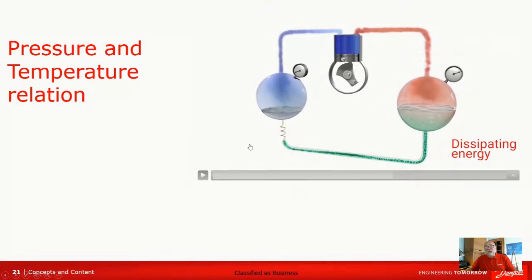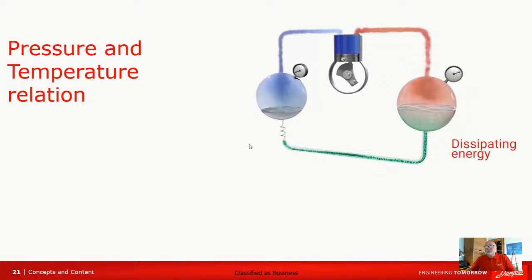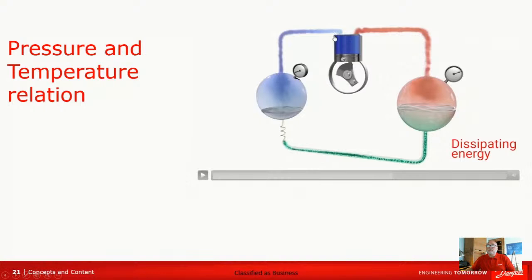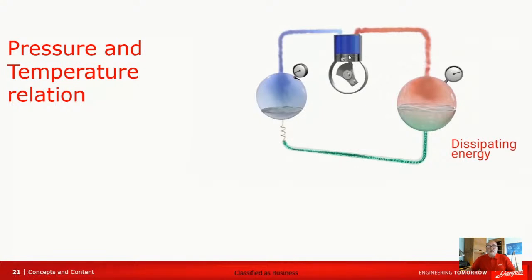So in principle, on a reciprocating compressor, if it turns one way or the other, that doesn't matter. The flow of refrigerant doesn't care. That is the valves taking care of that, and the piston. The piston just jumps up and down, and will do so regardless what way the motor is turning.